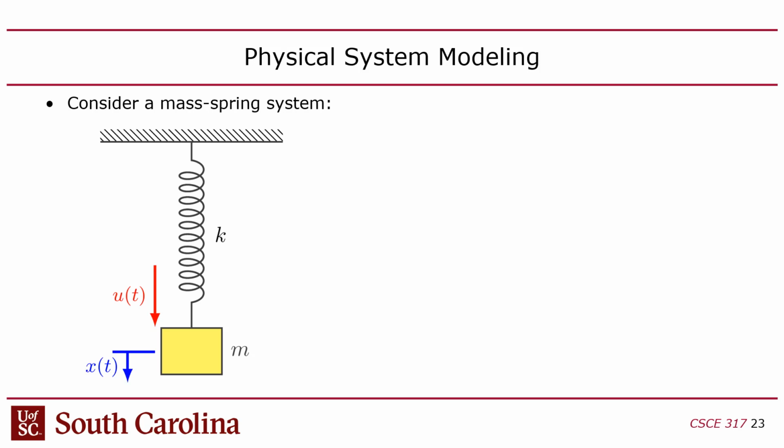There's a constant there. Now, you can model this as a linear system. You might say, wait a minute, is it a linear system? Well, no, in real life it's not linear because springs have limits. If I push it up, eventually the spring gets to the point where you can't compress it anymore. It's going to turn into a solid block of metal. Likewise, if I stretch the spring out really far, at some point it's just going to break. Those are the nonlinearities. But if I assume the spring has infinite flexibility, then it's a linear system.